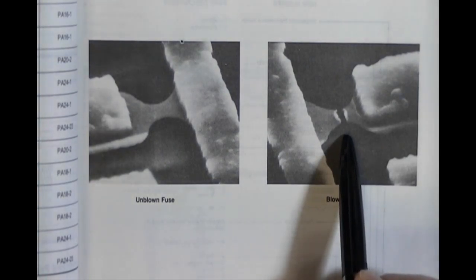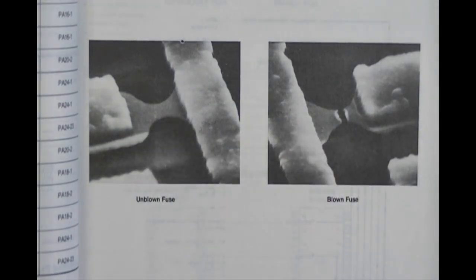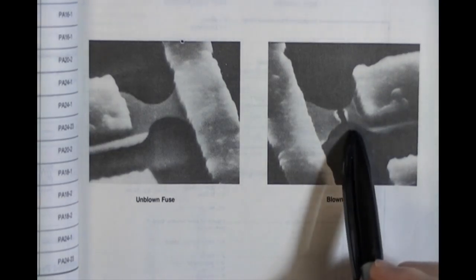No. To do this, you're talking about hundreds of milliamps and a high elevated voltage and enough current behind the delivery of the pulse to pop this fuse sufficiently so that what you have is a 1 instead of a 0. And this is why you can't reuse a bipolar prom, because once it's blown, it's blown forever.